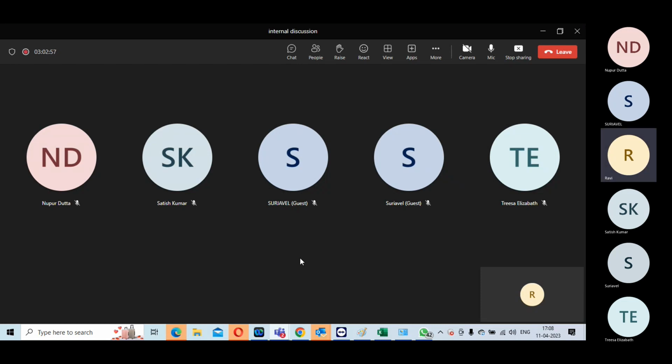It's not just for timing fixing, it's also for shorts. In that area, you have to fix shorts. It's highly congested, shorts are there, you don't have timing, how will you do it? You'll have to remove some buffers. How will you remove them? You have to look at the paths which are actually meeting timing. Wherever you have more positive slack, where it's meeting timing, downsize. Remove buffer, grab that area, create area, and give that area to these things. This is the way you have to do it.